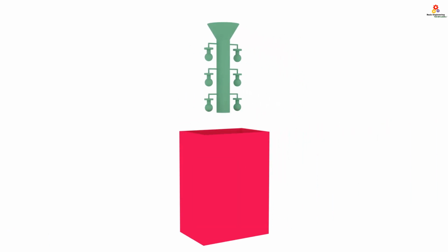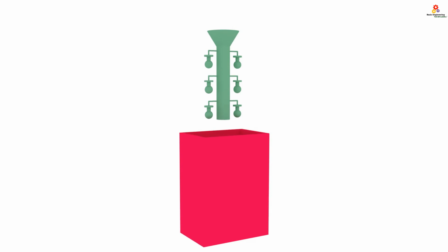Now we will make a mold cavity to pour the molten metal inside it and create the casting product. Let us dip this tree inside the ceramic slurry mixture to have a ceramic coating on the wax pattern as well as on the sprue.